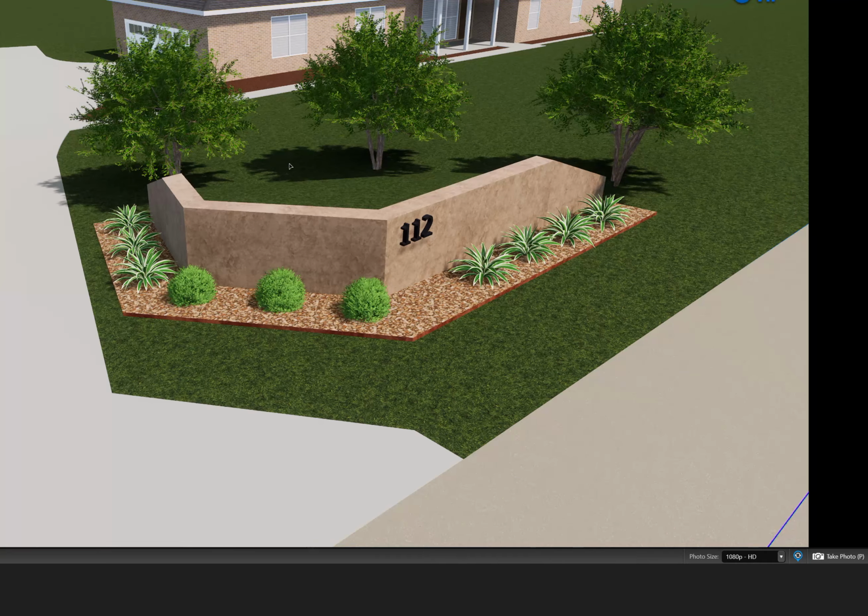Alright, the wall itself, again, is 1 foot thick. If you want to save a little money, we can do 8 inches thick. Then from a concrete perspective, I would do number 4 rebar, maybe number 5 rebar in your footings. It just depends on you. I'd probably do quite deep footings. We could do 36-inch footings if you want. It just takes a significant amount of time to dig them. The footings are what's going to make the difference on the wall anyway, to prevent the wall from kicking if it's impacted. Then I'd probably go with a heavier PSI, like 4,000 PSI concrete over our traditional 3,500 PSI concrete.